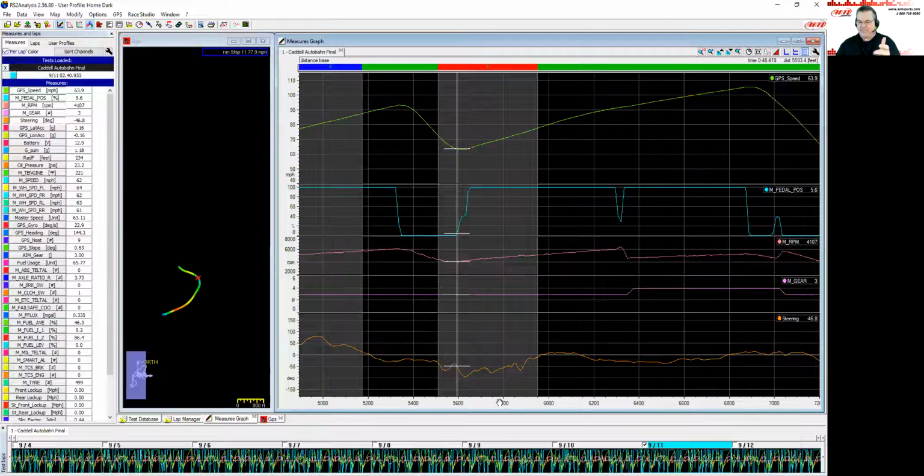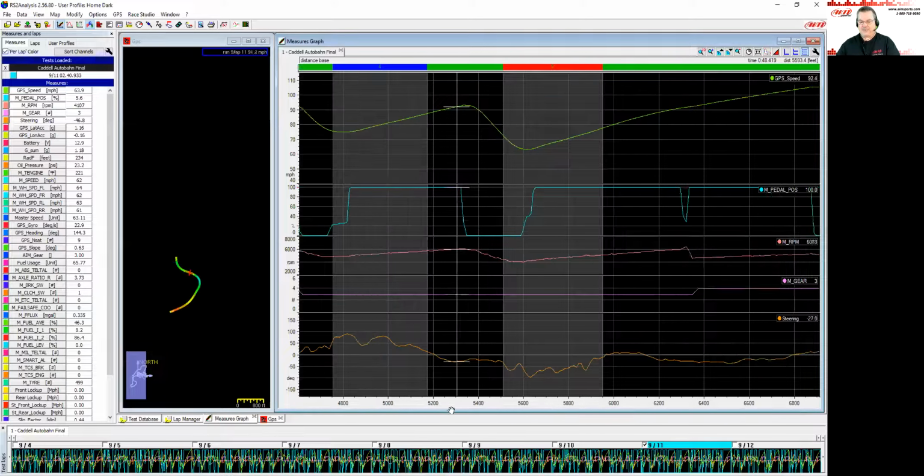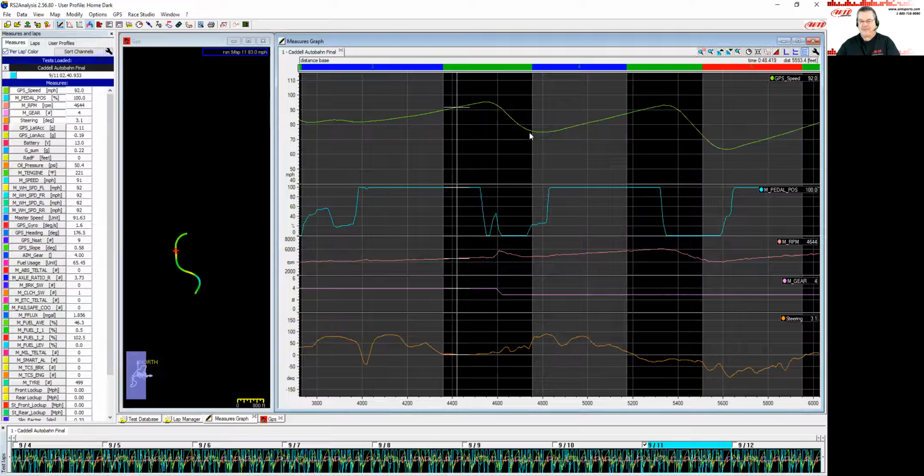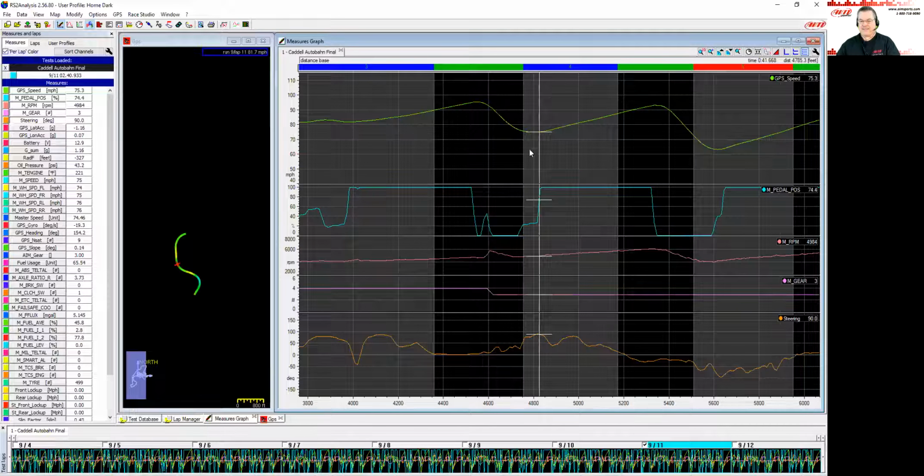One question that came up earlier that I noticed on Facebook about this topic is, now that I've zoomed in, maybe that corner back here is the one I really want to see. How do I move around in the window? When I'm zoomed in, you can take your mouse down here across the x-axis, and I can just grab this and drag this left and right by holding down my right mouse button and put that in the middle of the screen so I can see that particular corner, which is kind of handy.